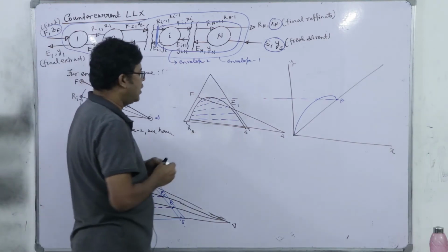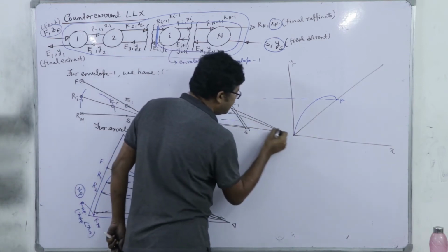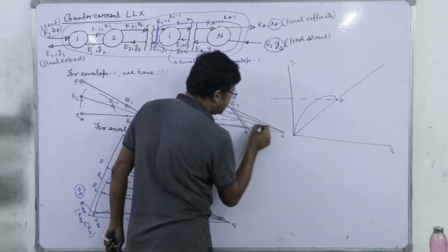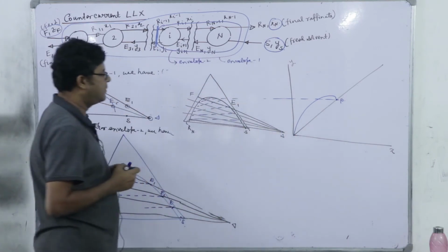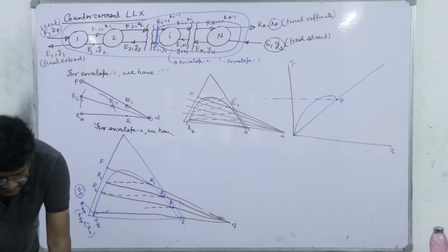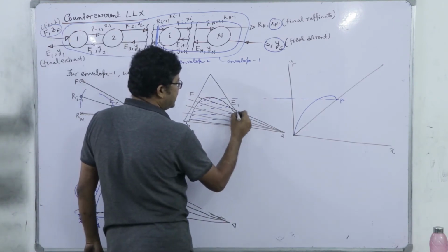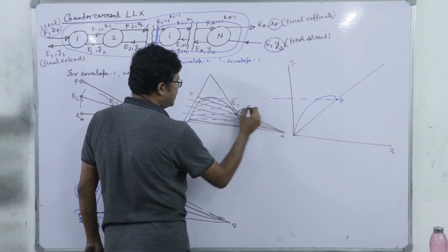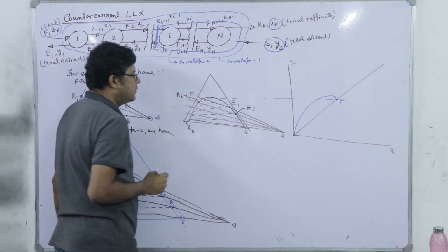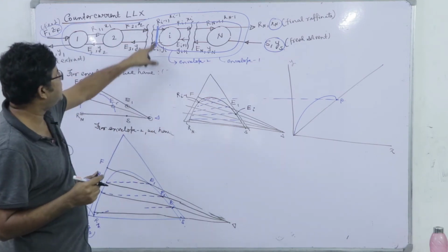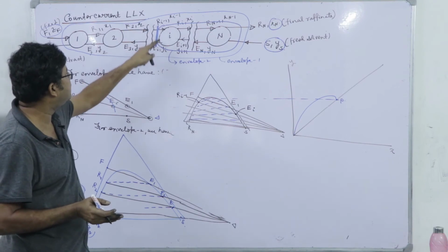So, if I draw some arbitrary lines from the delta point like this, they will be intersecting at probable E_i and R_(i-1), which are points on the operating line, because the operating line means something which will relate the properties of two countercurrent streams.